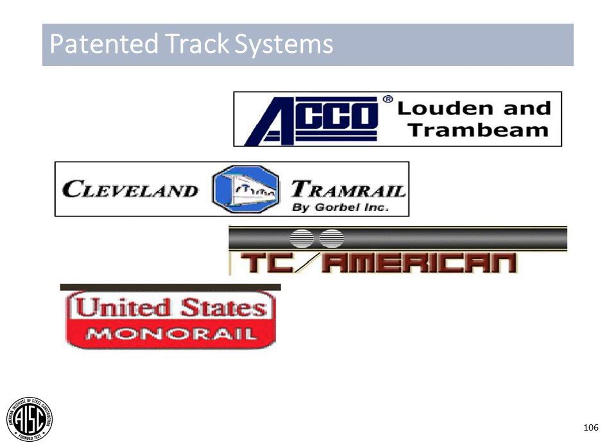There are a number of different ways that you can determine them. You can reverse engineer them. You can come up with an end stop that works for your system or that you've used in the past, and reverse engineer that to determine what the capacity is and list that on your construction documents. You can look at F equals MA, so you can look at the acceleration and the distance with which you need to stop the end truck to come up with the force.